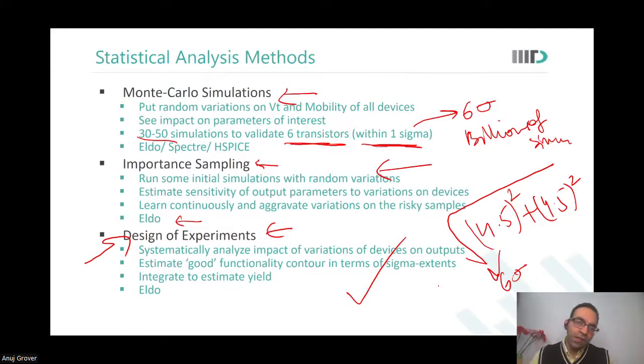Okay, sir. A fresh engineer who has not understood the design well cannot do this. You need expertise to even run design of experiments, because you have to know what experiments to design. For a memory cell, when I have understood the write margin, it is so easy to design. But think of implementing it for the self-timing paths. Can you design it? Can you distribute how much variation to put on which cells, which devices of which cells? Can you do that?